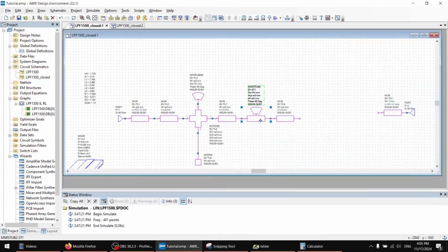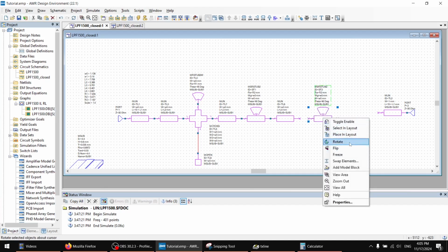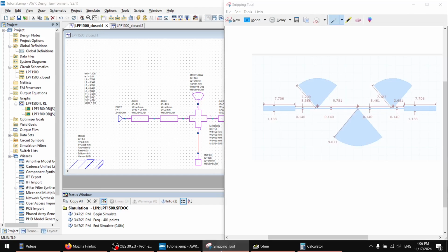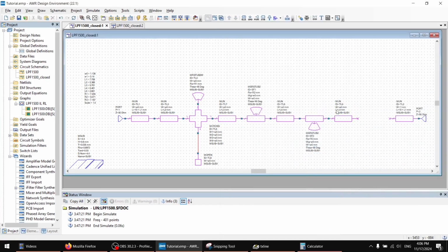And so we need another radial stub. Now we will place this. Now I will copy this and rotate this. I'm sorry that I'm confusing the shortcuts, but I was using Altium before and some of the shortcuts don't carry over between the programs, which is of course always annoying. So we want to set up here the radius number 3. The W0 is actually set up. There's another thin trace if I remember correctly. Yes, it is. So this will be our last, the L5, quite short little one.